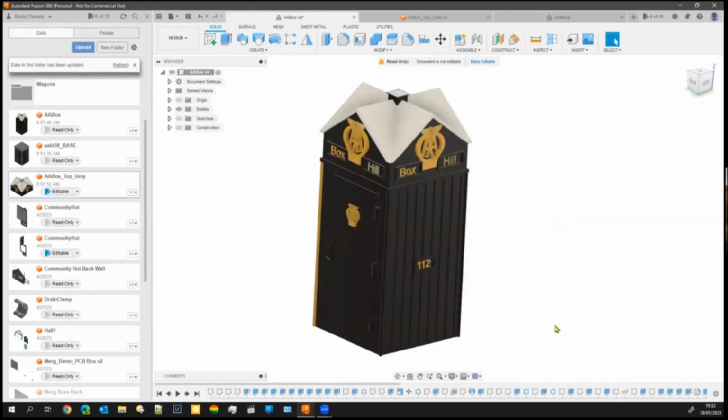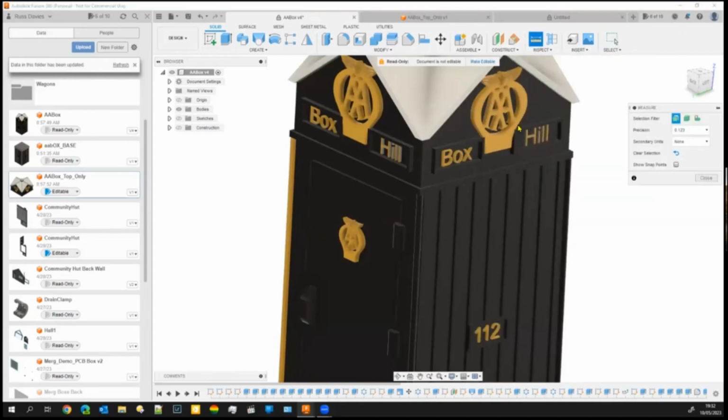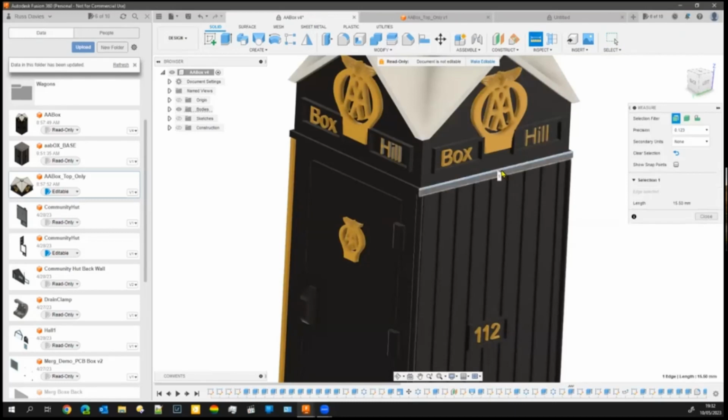Again, with the rider that whichever way I do it, there's always a dozen other ways to do it. So I'm not saying what I'm suggesting to you is the only way, far from it. So what we'll do, we'll make a start by now. The information we need to know to carry on from this is the size of this square here. So we can draw the bottom one, and that's 15.5 millimeters, basically, or 15 millimeters. And we can measure that by using the measure tool and just coming down on one of those edges, and we can see it's 15.5 millimeters, okay?